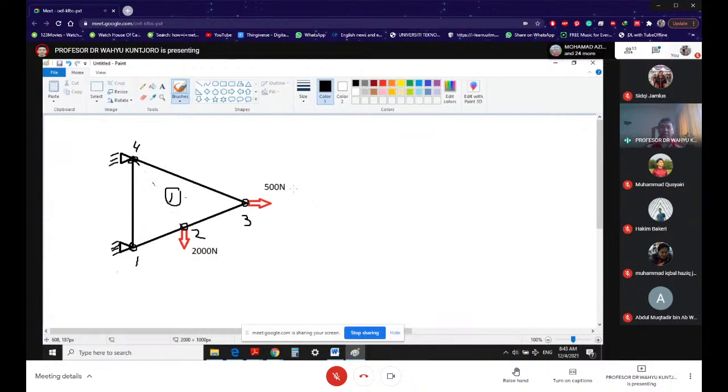The reason is because if you decide to have one triangle, you have an extra node over here. Based on what you have learned here, you cannot have a triangle with nodes at the corners and one hanging node over here. You cannot. So this is a wrong finite element model. The way you can do it, for example, is like this.